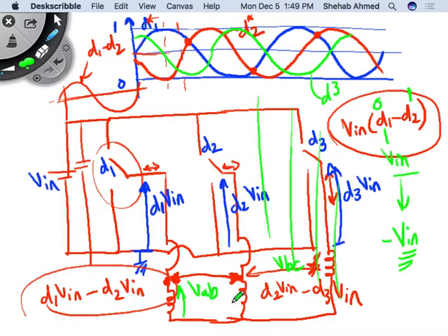That's related to what we did previously. This is a 3-phase star connected load. So the line voltage I can calculate. What is the phase voltage? The phase voltage is the voltage between this node and this node. How do I calculate that? Circuits. So it will be square root of 3 less, and the phase shift will be 30 degrees.